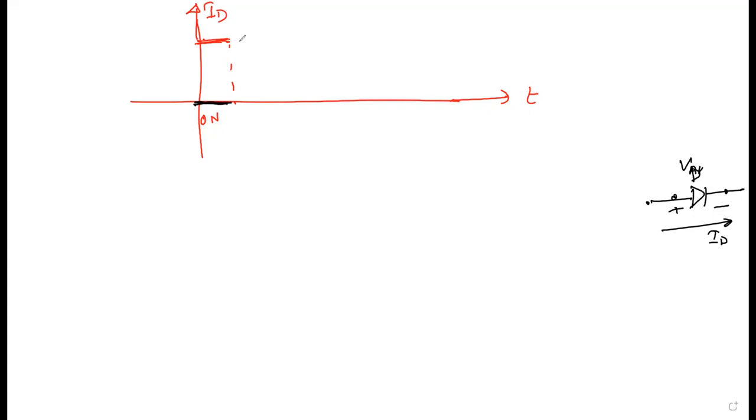When the diode is turned off, the current will not go to 0 immediately. Rather, it takes some time and goes like this. The current is 0 here, okay? If it stopped here, we would be very happy, but it does not stop here. Rather, it keeps going and stops here. This current is known as IRR, the peak value of the reverse recovery current. After that, practically, the current goes and finally goes to zero.